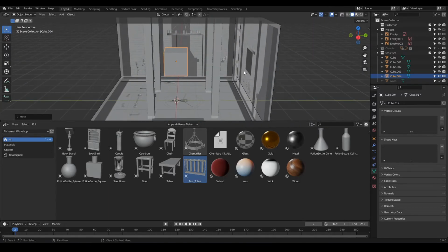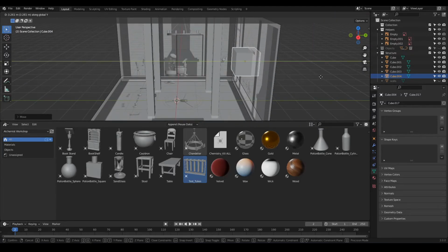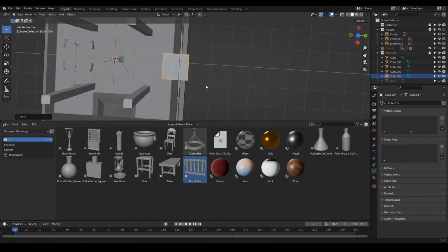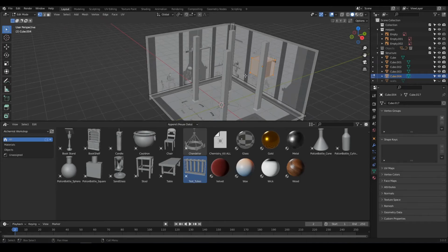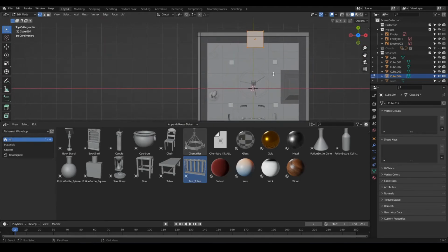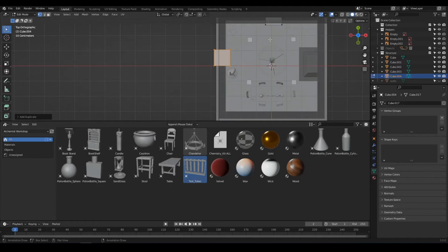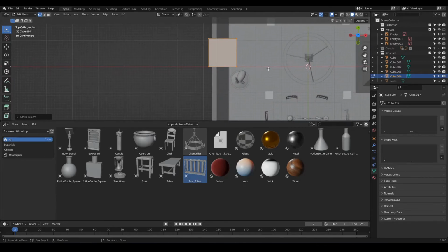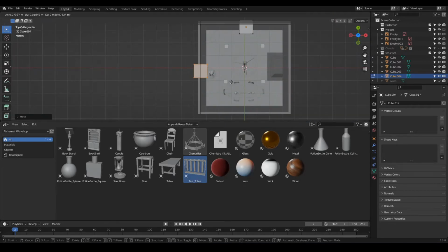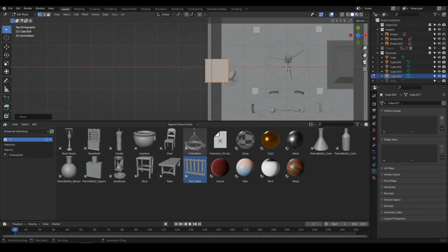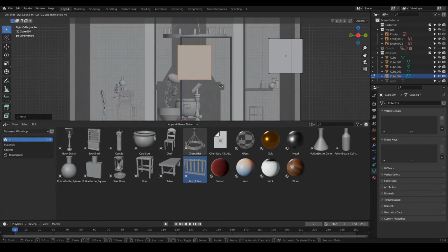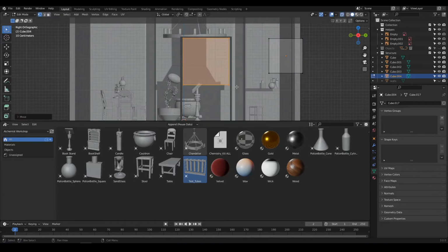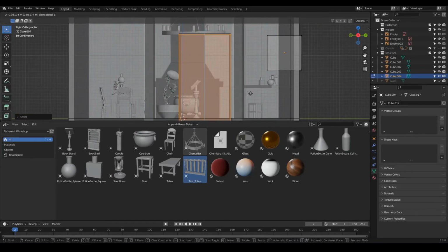Okay. I'm gonna move it here and I'm gonna use it as a boolean with the walls, and the same with the door. So I'm gonna duplicate the mesh while in edit mode so that those are the same object. Place it somewhere here, so it will be where the door will be, and then I will give it the shape of the door, which is about okay.